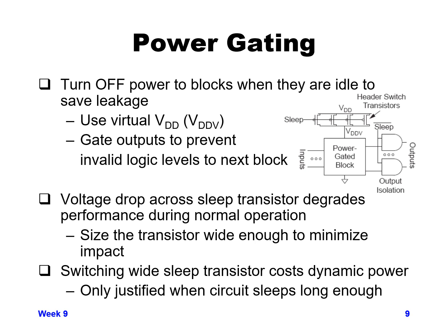One thing to keep in mind is there will be a slight voltage drop across your sleep transistors, and that slight voltage drop will degrade the performance of that power gated block in normal operation. But as long as you make the number of parallel sleep transistors large enough for the amount of current that needs to be provided to the block, you can minimize that impact and see a fairly small impact to your overall power while you're doing real logic, at a pretty dramatic decrease in your leakage power when you're trying to turn it off.